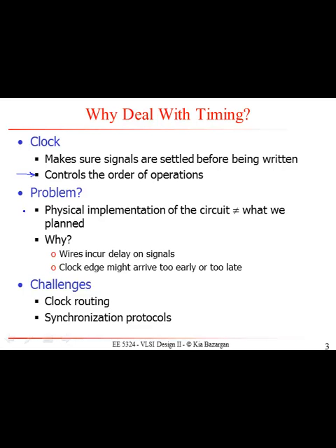And if you remember in the intro slides, I talked about clock frequency going up and that resulting in dynamic power going up and all kinds of thermal issues and so on. So people have been talking about maybe you can run different clock domains, and at some part of the chip you could run it at say 5 gigahertz, but the bus that is moving data between memory and that functional unit could be running at 1 gigahertz.